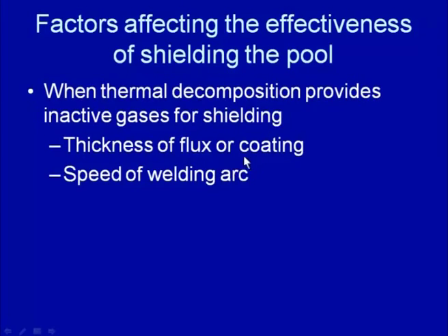So, the thickness of the flux is important when this approach is used. If the coating thickness is very small, then an insufficient amount of shielding gases around the arc will decrease the effectiveness of this method.